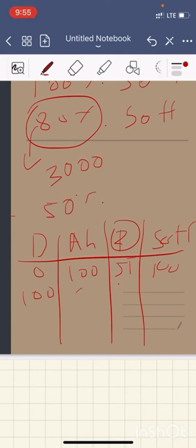On day 100, the capacity is going to be 98 AH, and the resistance is going to increase by 2 milliohm, let's say from 55 to 57. SOH is going to become 98%.